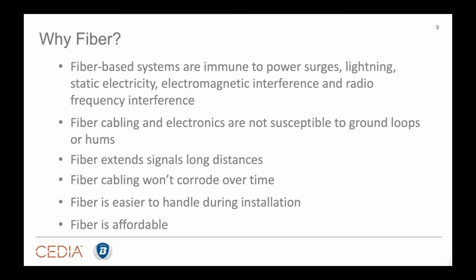There are reasons we integrate this, and we have for quite some time, 5 decades. Fiber systems are completely immune to power issues like surges, static electricity, lightning. They're also immune to interference. So if you've ever had a twisted pair extender lock up, maybe you install everything, works great, get a call 7 days later, no picture on my display, power cycle the thing, it works again. Well, that's caused from interference. Fiber's immune to that. No RF, no electrical interference, okay?